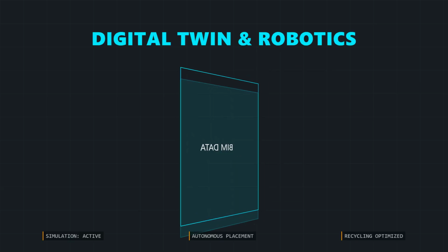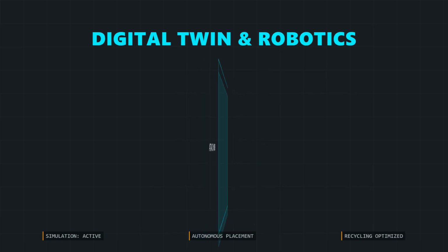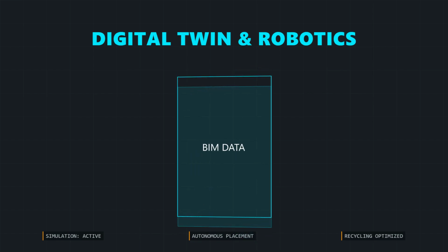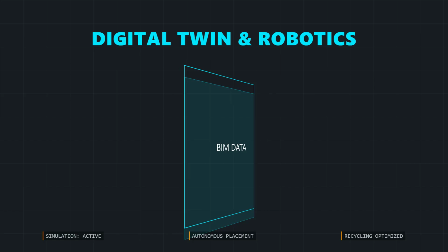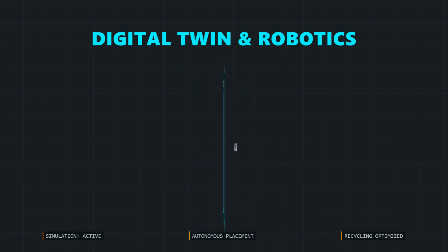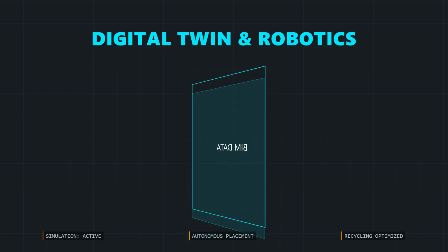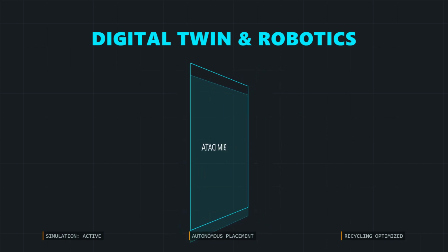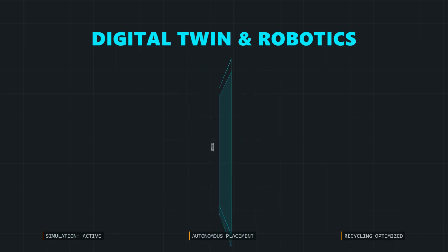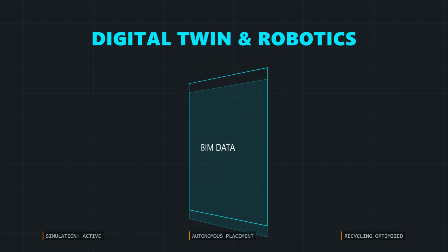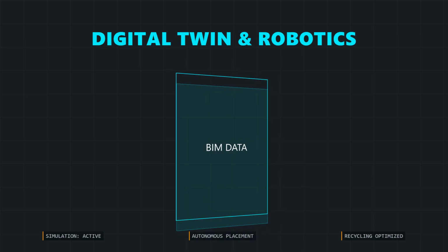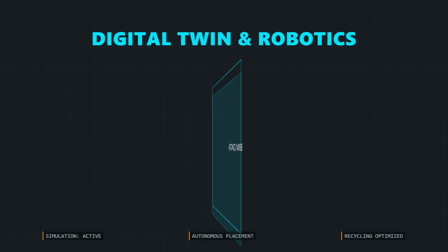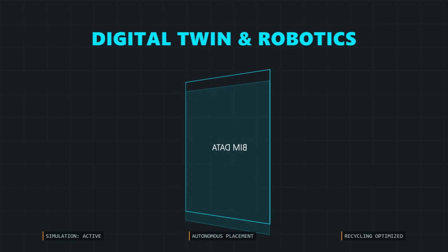The future of demolition integrates advanced technology to enhance precision and maximize material recovery. Building information modeling, or BIM data, is used to simulate collapse dynamics with extremely high fidelity. This simulation optimizes charge placement and refines timing sequences in virtual environments before physical execution. Robotic systems are increasingly deployed for charge placement in hazardous or structurally unstable buildings. This deployment significantly improves worker safety margins by removing personnel from high-risk zones.